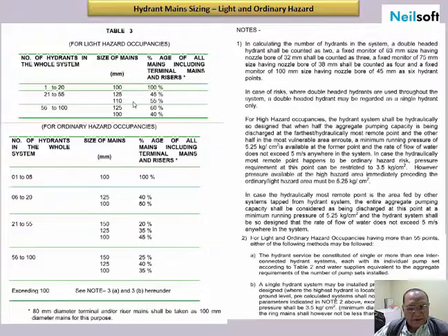So to my understanding, generally this pipe diameter is not manufactured. So for the practical purpose, for these categories, we can use the 150 mm dia when the number of hydrants is within this requirement. So this makes an easy selection for the main sizes.